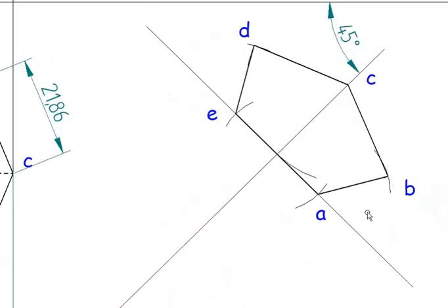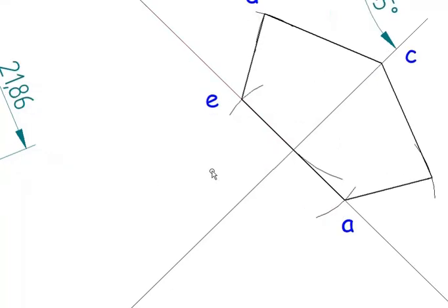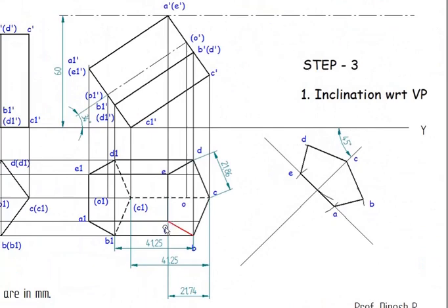Once this is drawn, you can just delete it. So make sure this is going to be exactly perpendicular. After drawing this, I know all these edges are going to measure 41.25. So even if you select it, 41.25, 41.25, 41.25, even the distance from O to O1 will also be 41.25, A to A1 will also be 41.25.